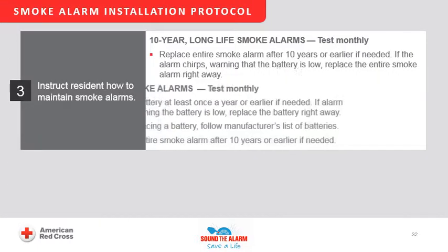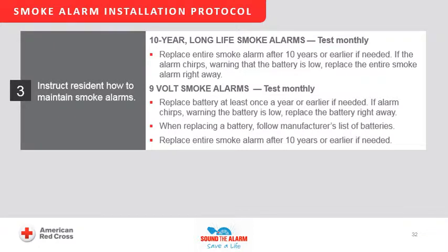3. Instruct resident how to maintain smoke alarms. For 10-year long-life smoke alarms, test monthly. Replace entire smoke alarm after 10 years or earlier if needed.